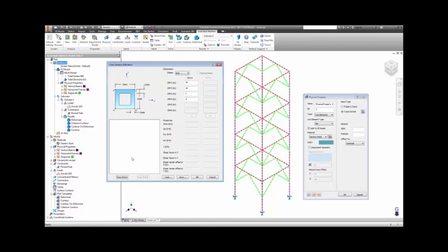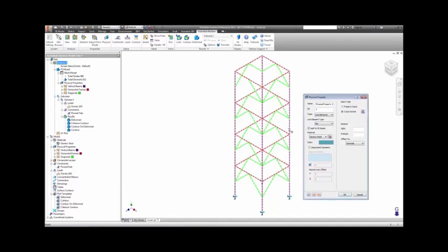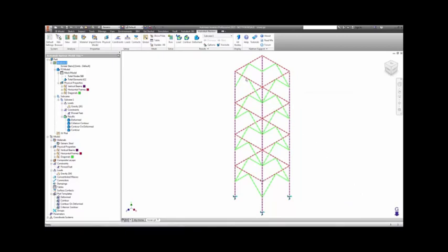You can click down here and it'll show you what your beam section would look like. Once you've made your properties, you can assign them to different parts of the model so that when it's meshed, different areas will also have different beam sections. This particular model has 3 different properties: one each for the diagonals, the horizontals, and the verticals.